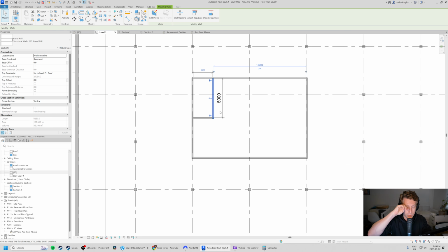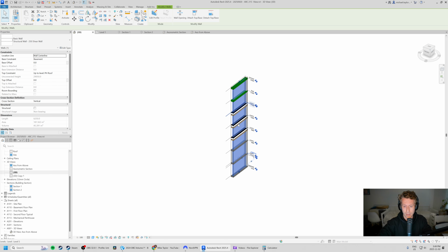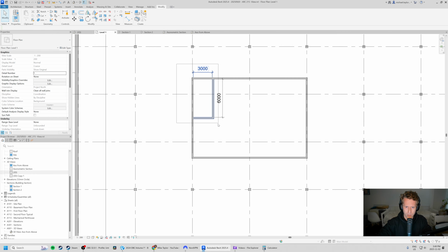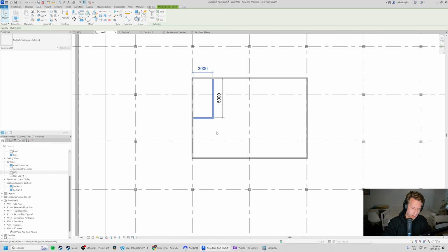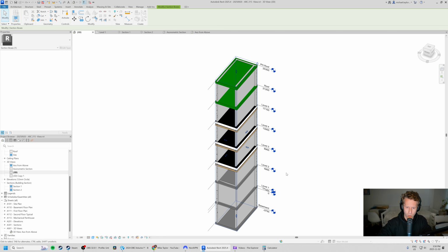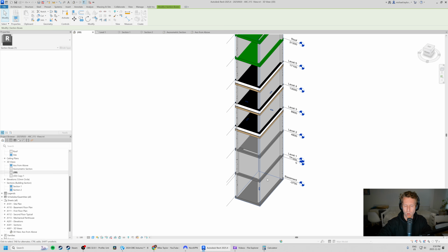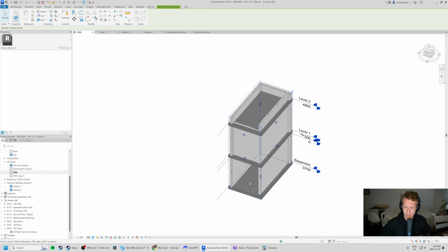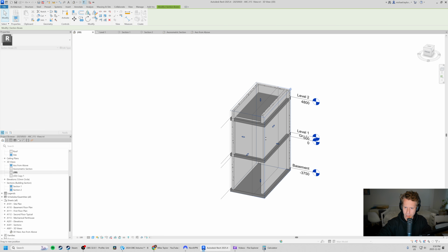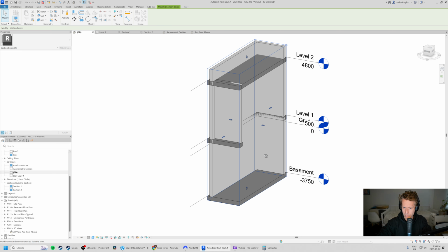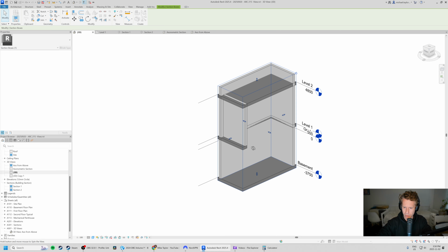If you remember, I like to use the box tool. So the box tool automatically sets up a section box around some element that you are looking at. Unfortunately, it's not ideal. Let's do this whole thing here. BX, try that again. So this is my section box. It's set it up through the whole jam here. I do want to see, my hole is actually going to be at level 1. Okay, so that's okay, because that's what I told Revit to do, was to make it at level 1. So we could see here, good. It's pretty good. So we got a little idea of, again, I'm using my section box tool.